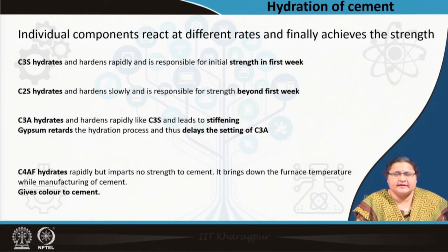C4AF, that is tetracalcium aluminoferrite, hydrates rapidly but imparts no strength to cement. It is important to bring down the clinkering temperature when the cement formation is happening.